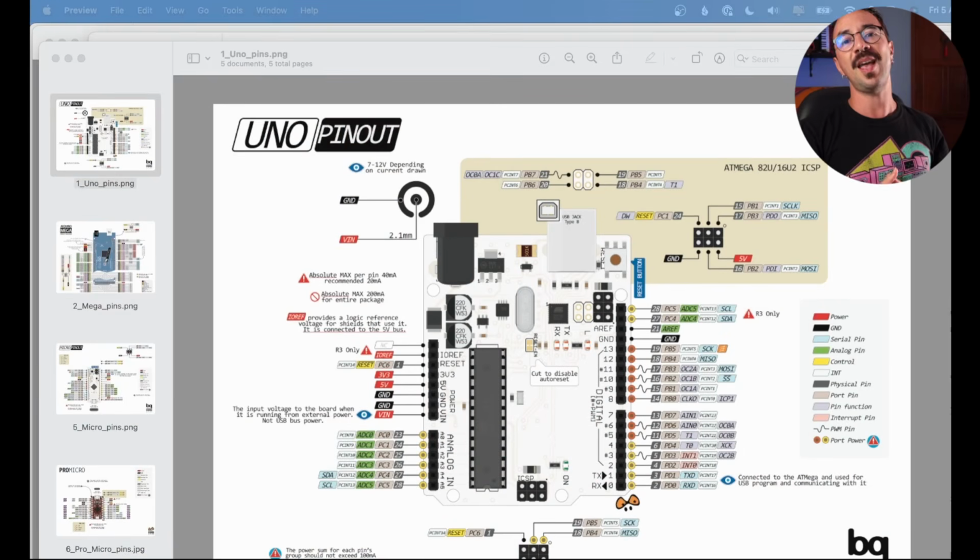So that's what you need with your encoder. When any of those pins change its state, you need to go to a certain function. With the library we're going to use, that's really fast. We don't need to worry about functions or anything like that. But we need to connect the A and B pins of the encoder to pins with interrupts in the Arduino. So which pins have interrupts?